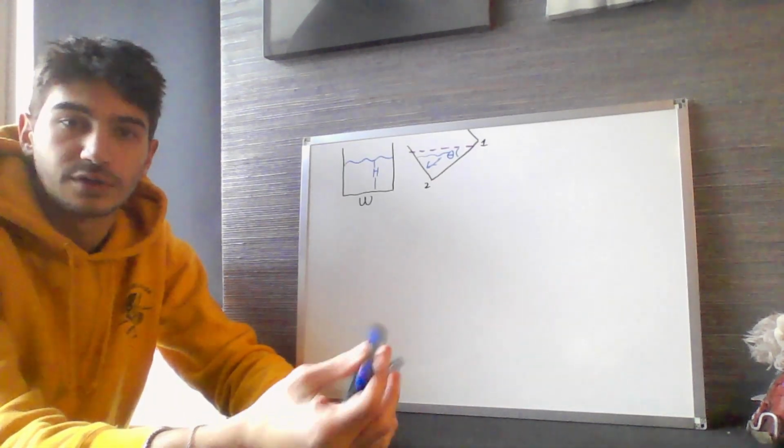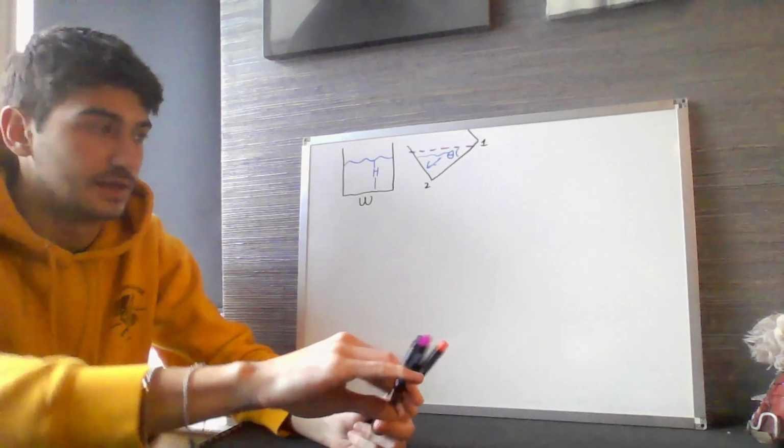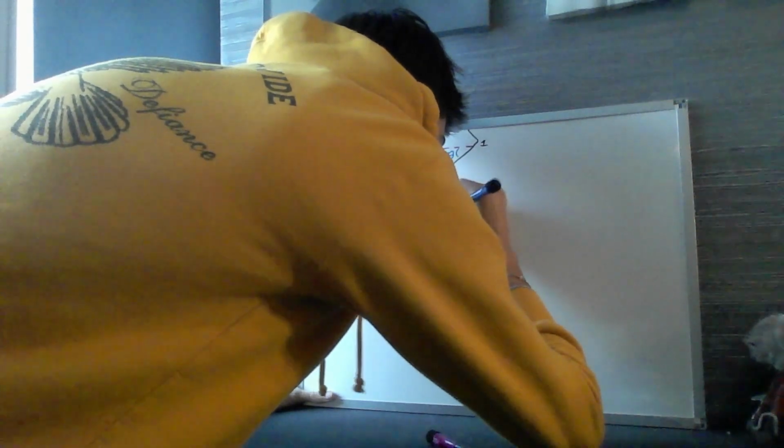And we always start with Bernoulli's equation. So let's go ahead and write that out. Of course, that is the difference between the two pressures, P2 minus P1 divided by its density rho, plus the values of the two velocities, V2 squared minus V1 squared over 2, plus the heights, Z2 minus Z1 times g, equal to negative 4f V squared over 2D.